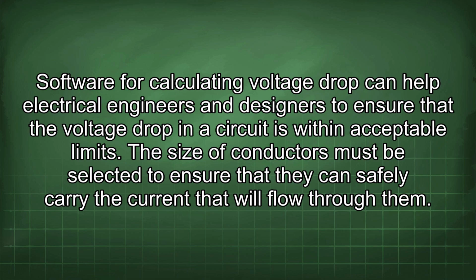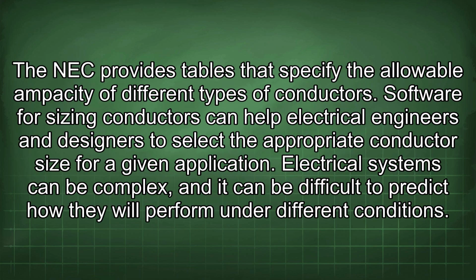The size of conductors must be selected to ensure that they can safely carry the current that will flow through them. The NEC provides tables that specify the allowable ampacity of different types of conductors. Software for sizing conductors can help electrical engineers and designers to select the appropriate conductor size for a given application.